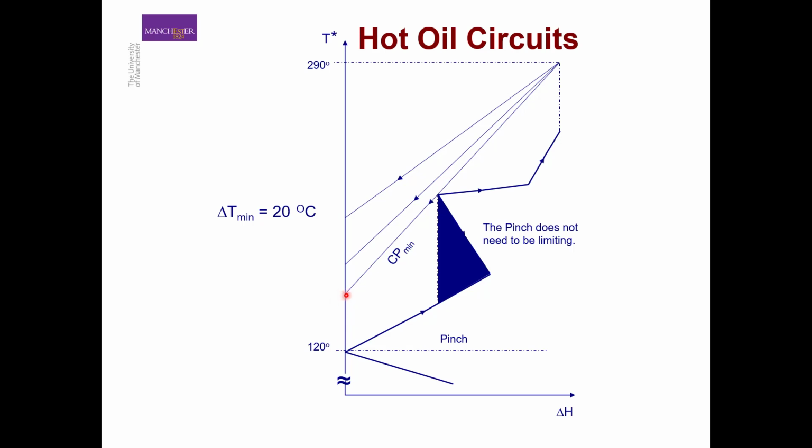And again, if we want a higher return temperature, it means that we have to increase the mass flow rate of the oil. And by increasing the mass flow rate of the oil, we have to provide extra pumping to the process. We have to provide more oil to the process. So that is not optimum in any case. So if we cannot get a return temperature of the oil at the pinch temperature, then we have to use the next best guess, that is touching the Grand Composite Curve and then using the temperature that is here, for example.